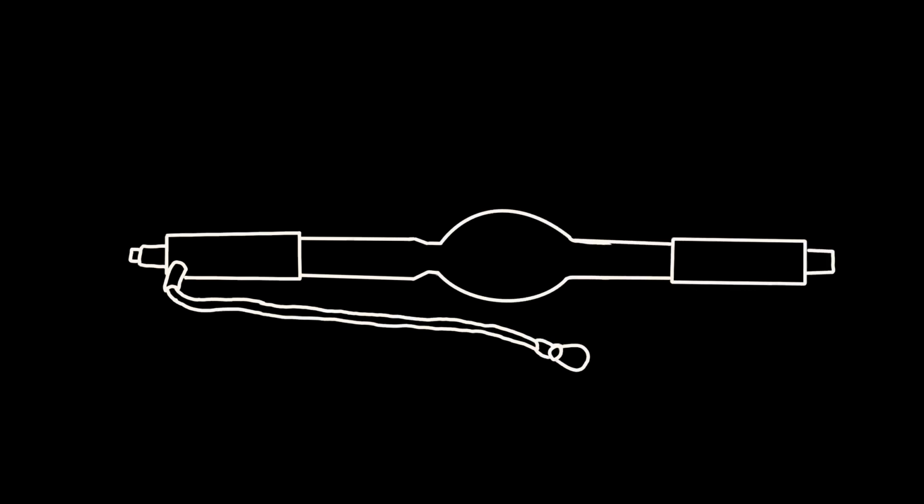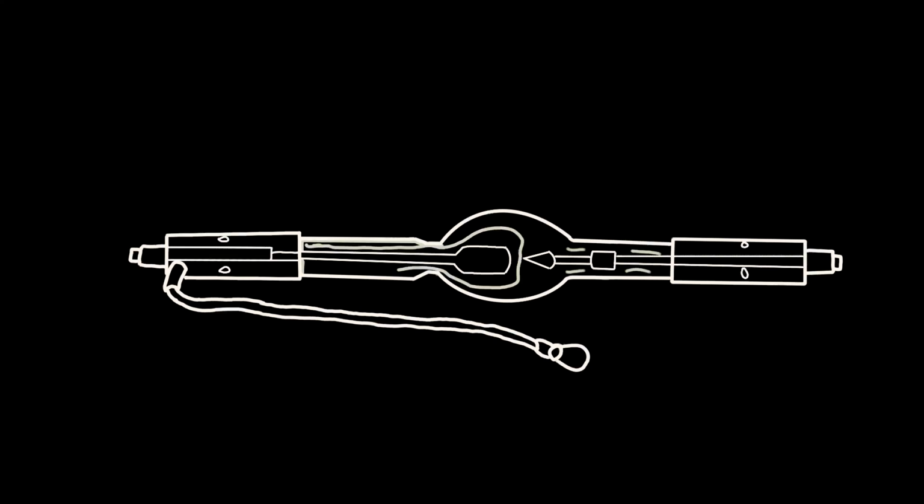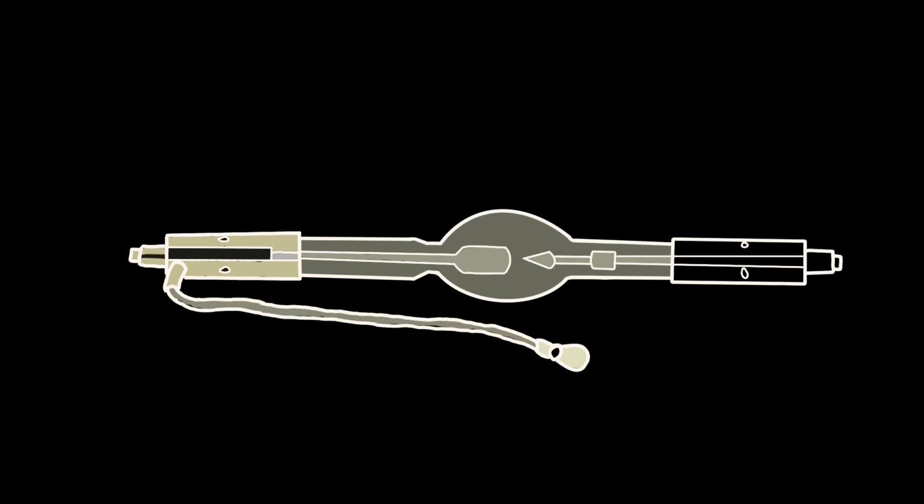UHP, ultra-high pressure lamp, is compact, extremely efficient, and has good lumen maintenance. It has a cooler color temperature between 7 and 8K Kelvin and typically has a limited lifespan. The other lamp type is the xenon arc lamp, where white light is produced by a xenon bulb, which is better saturated in the three primary colors, is in the daylight color spectrum, and requires high power. However, it has poor lumen maintenance and will flicker toward its end of life.